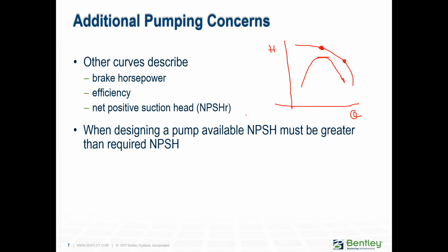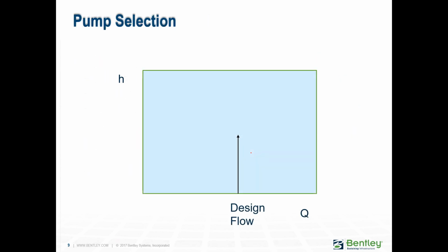The pressure is so low that the water turns into vapor, and it creates these pockets that damage your pump's impeller. So you never want to get there. The manufacturer tells you the minimum suction head that you need so that we don't have cavitation. So you always want to be checking that net positive suction head.